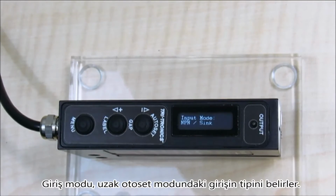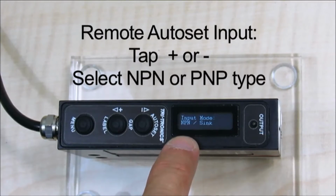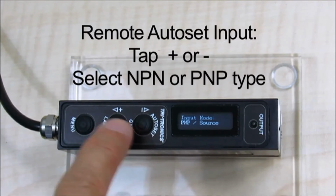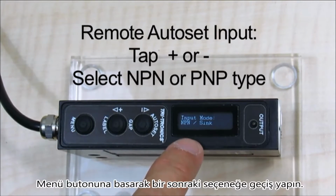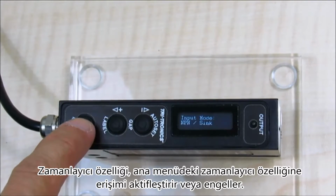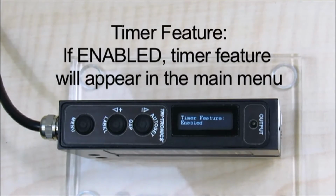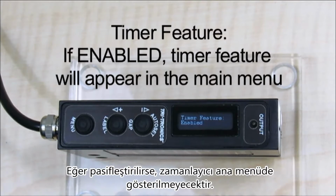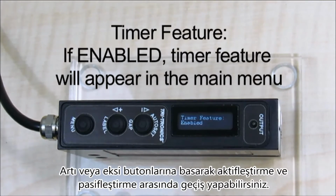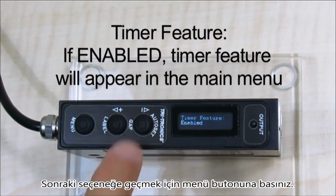Input mode specifies the type of input the remote auto-set input will be. Tap the plus or minus button to toggle between NPN and PNP type inputs. Tap the menu button to advance to the next option. Timer feature enables or disables access to the timer feature in the main menu. If disabled, timer will not be displayed in the main menu. Toggle between enable and disable by tapping either the plus or minus buttons. Tap menu to advance to the next option.